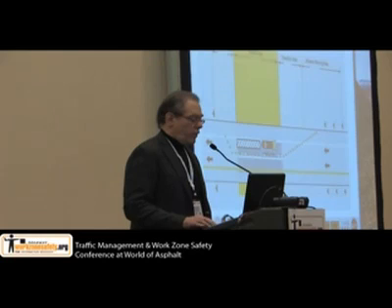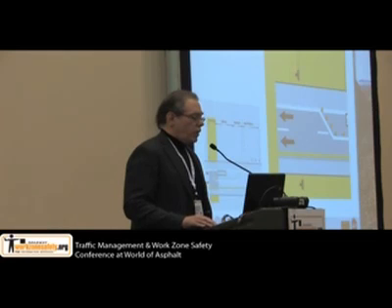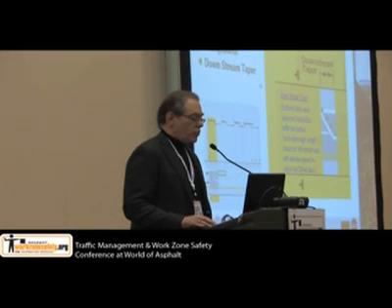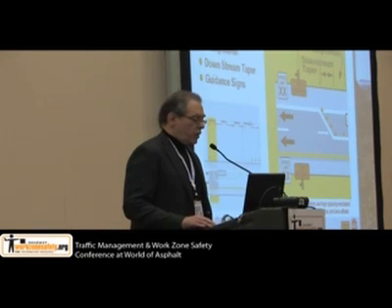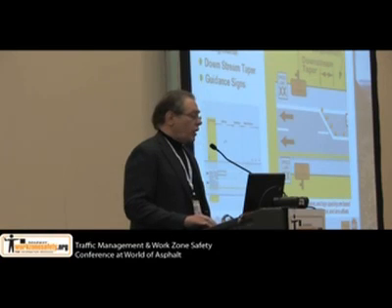And then finally we have the termination area. In the termination area we let normal traffic flow resume. Parts may include a buffer space, which is longitudinal, a downstream buffer, and guidance signs that can be used before normal speed resumes. And again, notice that we still have over here, from our original diagram, a locator objective to keep us in place where we are.